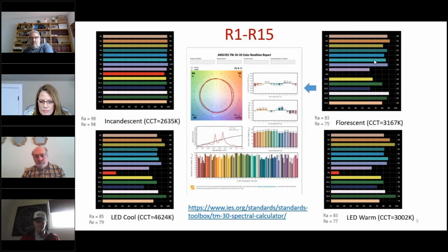It happens that for some lights, for example, if you look at outdoor lighting, sometimes if you measure it, you see the R9 is negative. It's because the calculation of the CRI is in such a way that it would allow the indices to go negative. It's very sensitive to the red, and it could go negative.